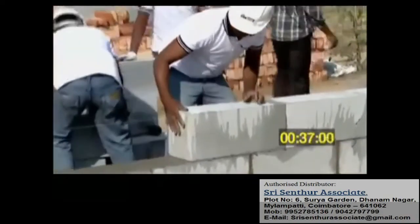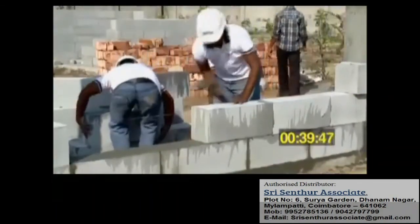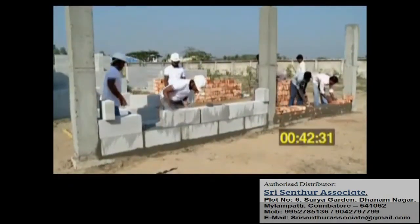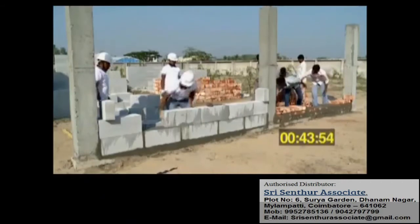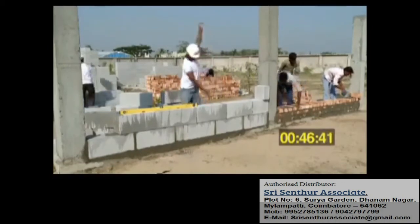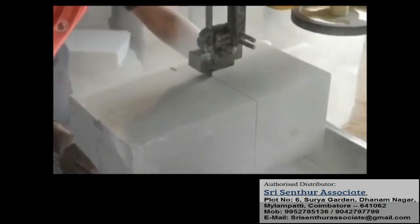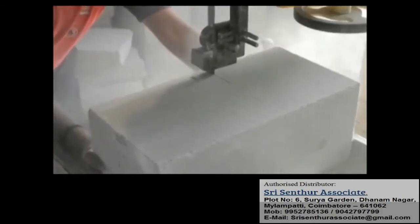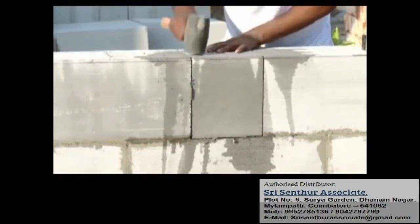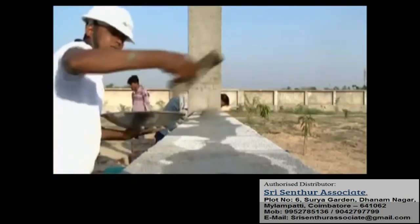Walls with AAC blocks can be built much more rapidly than red clay bricks because it is easier to handle due to its lightweight despite the large dimension. A water level is used to ensure that the wall is horizontally straight. Another gain of AAC blocks is that they do not require curing as required for red clay bricks. Just a sprinkle of water is required before applying the thin layer of mortar.